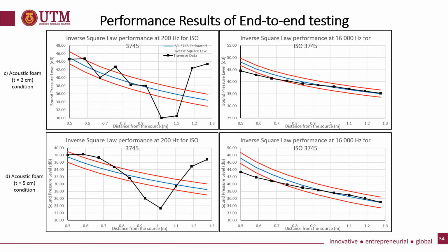So, in short, both tests have shown that the chamber can perform well for high frequency testing due to the foam's ability to absorb sound or noise externally. However, the chamber will perform badly with low frequency testing, which can be observed from the graph I've shown before. Therefore, for future testing, it is important to determine the frequency of the equipment first before testing inside the chamber can be performed.